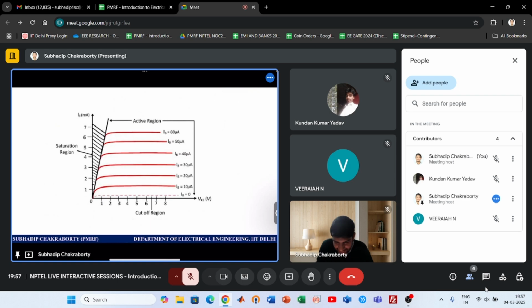So you see the output characteristics, what you can judge is that initially, keep that structure in your mind: it is the NPN, and this is collector, this is base, this is emitter. What we do, we choose a source, VCC we call it, but we have a resistance, because to protect the device or for some biasing action we need to provide a particular VC. Similarly we have a resistance here, RB, and this is RC, and this is RE, okay, and this is ground.